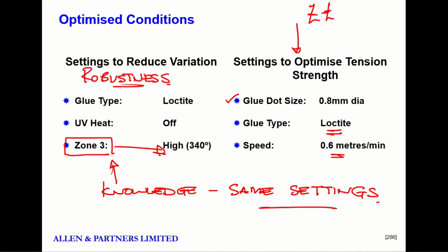We used to spend days trying to find unique product settings because of the unique thermal mass on the circuit board. But after this DOE, every job had the same settings. This eliminated setup time and fiddling about and development time and all kinds of things.